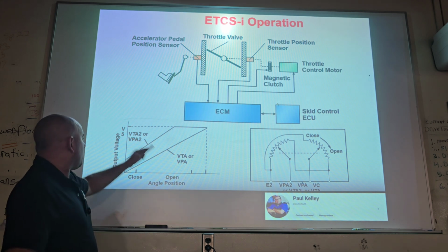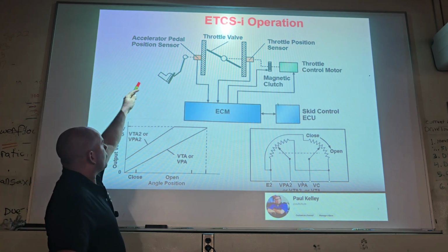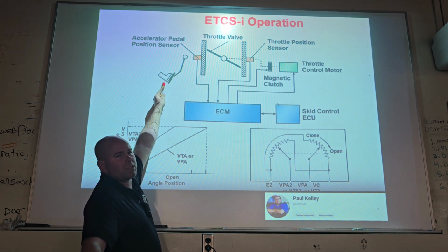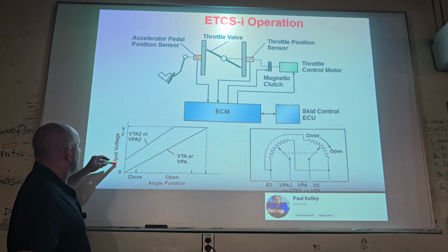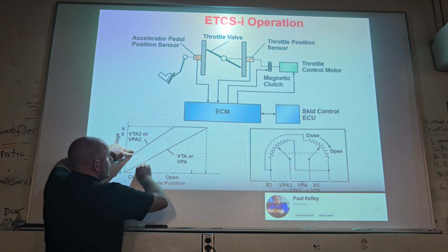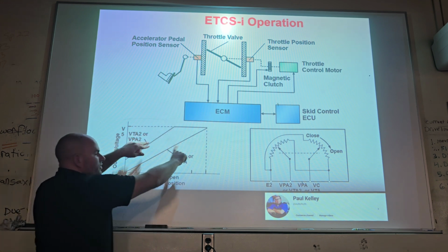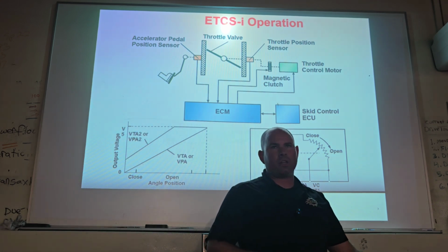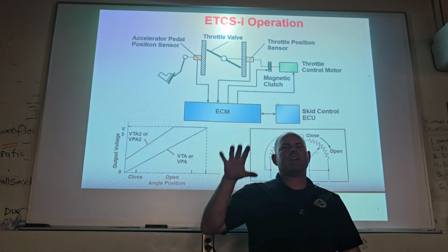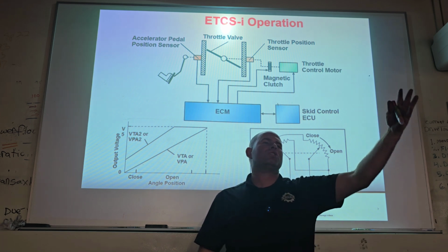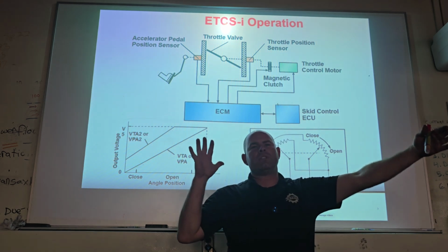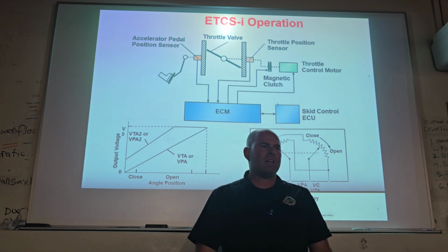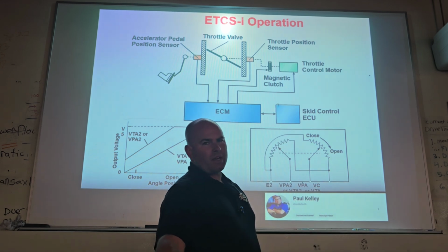So a lot of times you got a redundant throttle position sensor and a redundant accelerator pedal position sensor. That's right here. You have two sensors in one housing and they have to agree. All right, so this is where people say, I don't want electronics, I want a cable, electronics aren't safe. You mean to tell me that if that sensor malfunctions, it'll have my engine accelerating and my foot's not even on the pedal? You guys remember I told you about the Priuses that would self-accelerate and all that stuff? I'm gonna tell you why I'm not a believer in that. Real simple.